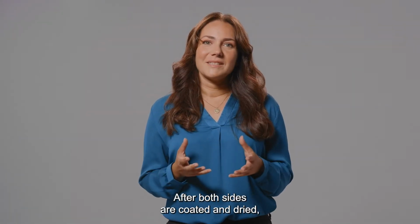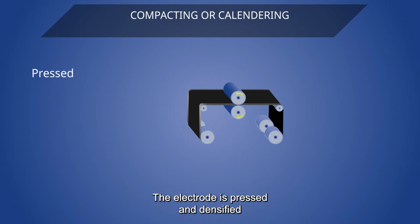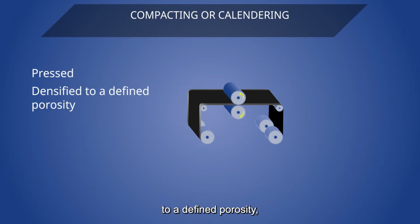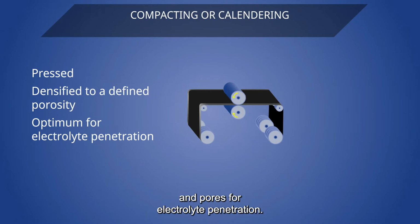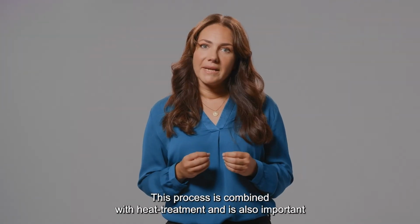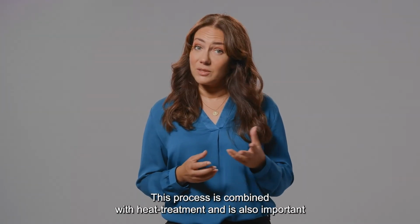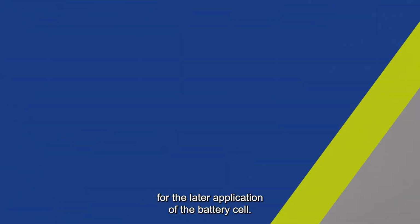After both sides are coated and dried, next is the compacting process. The electrode is pressed and densified to a defined porosity, providing an optimum between volumetric capacity and pores for electrolyte penetration. This process is combined with heat treatment and is also important for the later application of the battery cell.